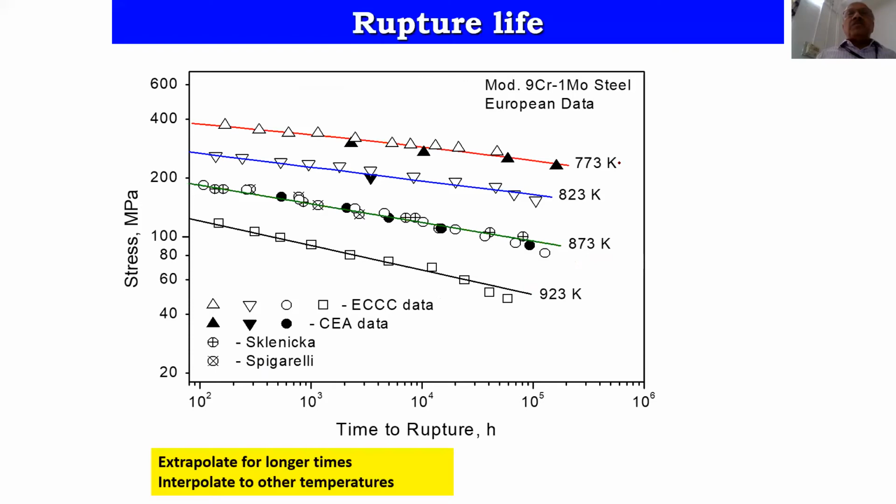So one can always do several tests, each test at one particular stress, and so many tests at so many different stress levels. So, as I said, at one temperature, you carry out so many tests, each test at one particular stress, determine the rupture time, and then you make a logarithmic plot, time to rupture on the y-axis and the stress, and you get one rupture curve. Like that, you can keep on doing tests at various temperatures, and this is normally the kind of data that one gets in a creep test.